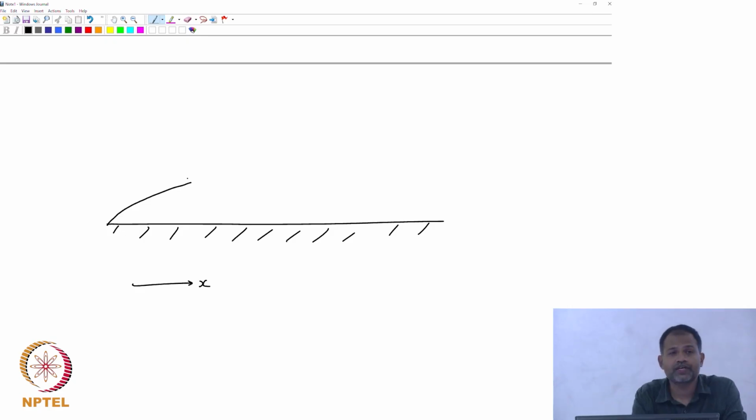So let's say that shows the growth of the boundary layer. If the Reynolds number gets sufficiently large, then even though the flow would be laminar near the leading edge of the plate, after a certain point it will actually turn turbulent. So if you were to track the boundary layer thickness, you would see that it nicely grows like root x, and then suddenly at some point it will start increasing rapidly, and then again it will slow down.